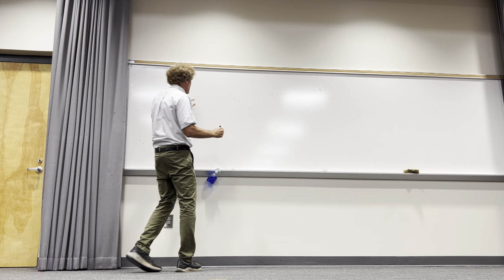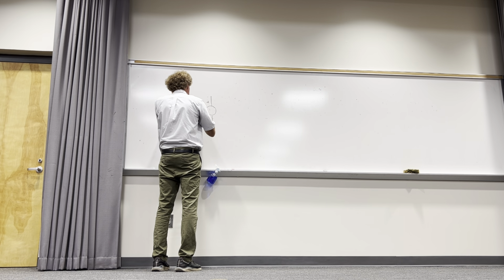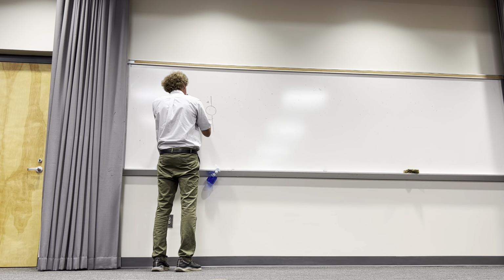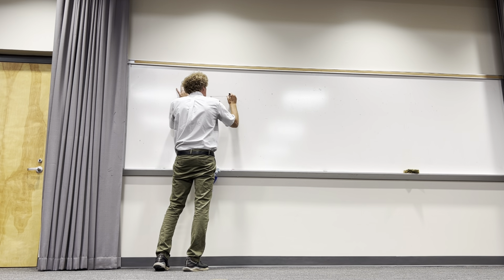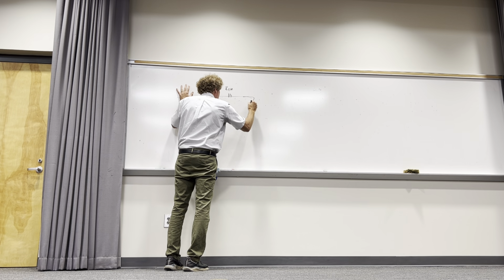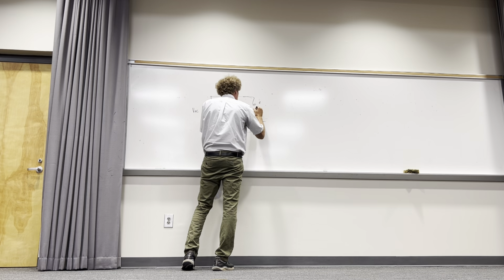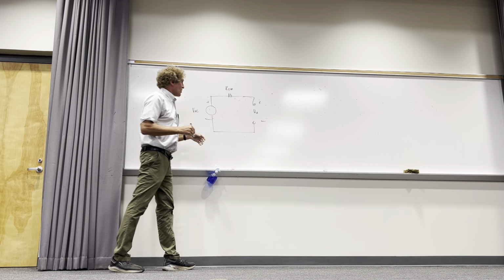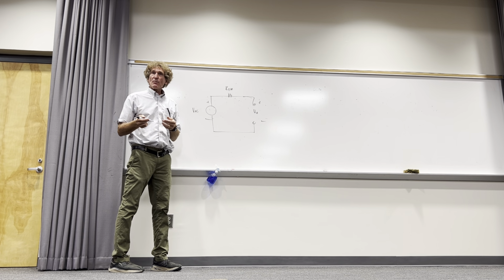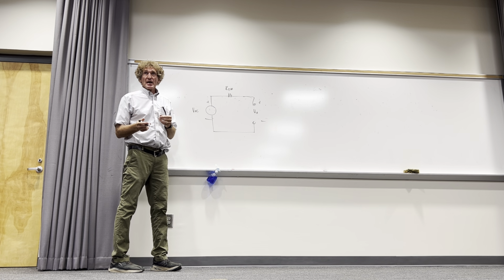Now, just hear me. If I have a voltage here that I'm just going to call V open circuit, and I have a resistance here, and I'll just call it R Thevenin, and then here is where I would find the actual output voltage or the output current. Y'all with me? That would be the equivalent Thevenin circuit for any combination of resistors and current sources. With me? Or voltage sources. You can always boil it down to that.